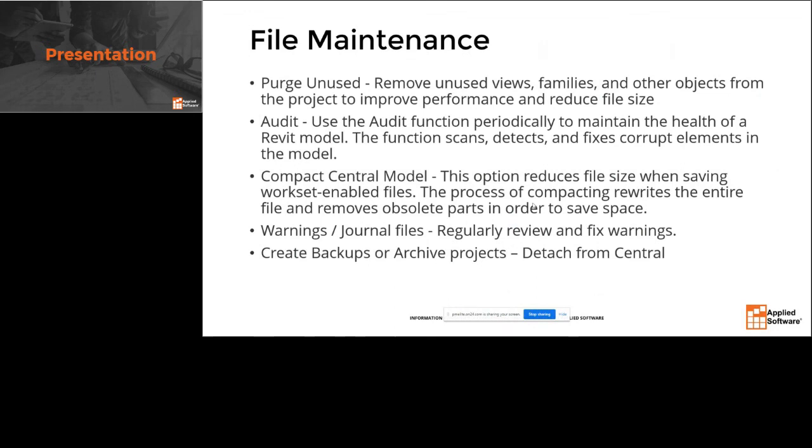A good purge is really going to help improve the performance of the model and reduce file size. So doing it that late in a project is okay. The audit functionality is upon open only.